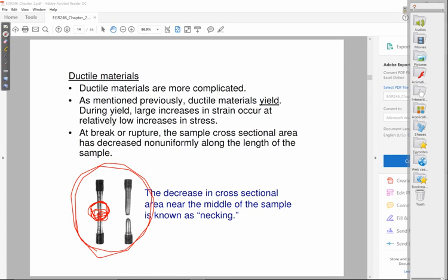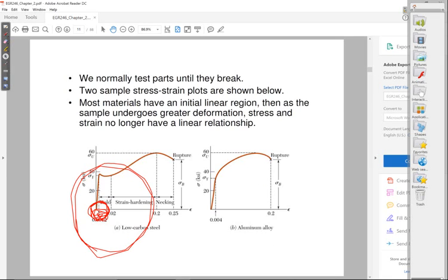And we're willing to forget about that, okay? Because that only really comes into the picture when it starts to deform quite a bit. And if you look at our plot for steel, where does it really start to deform? It really starts to deform, kind of starting at the yield region, but definitely in the strain hardening region. And, as far as engineers are concerned, we don't care too much about what goes on in the yield, the strain hardening, and the necking regions.